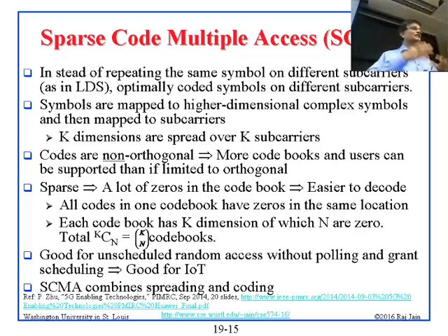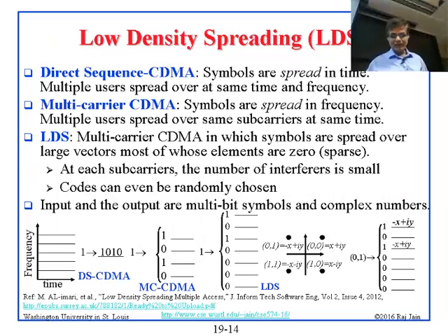Okay, so you have the full space, and more code books, and therefore you can have more users and more code books. By the way, each user, when they have one bit, they just need to know one entry, that one is this one and 0 is opposite of that. But if you have 2 bits, then you need 4 entries. If you have 3 bits, you need 8 entries, right? So that becomes a code book.